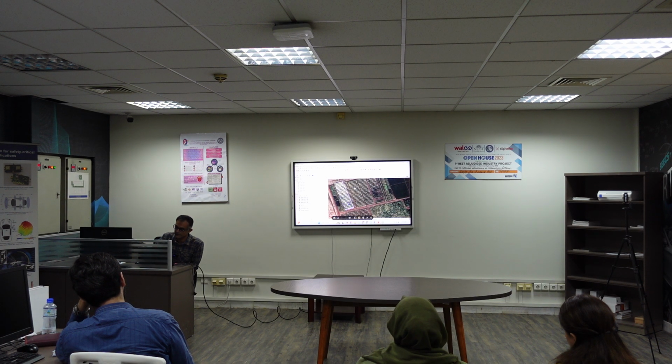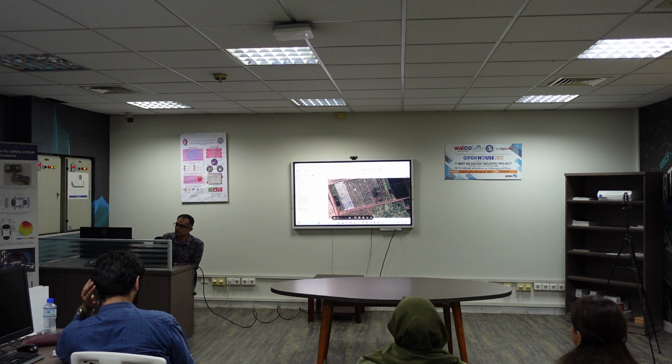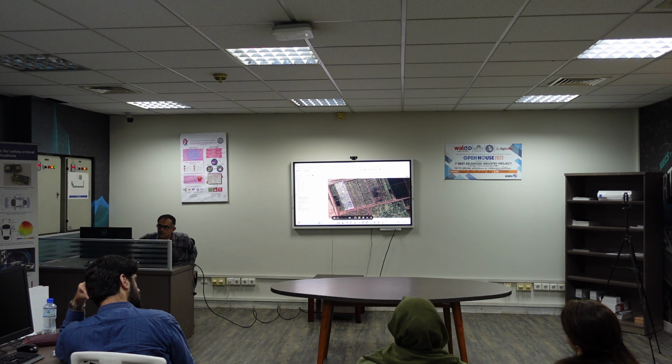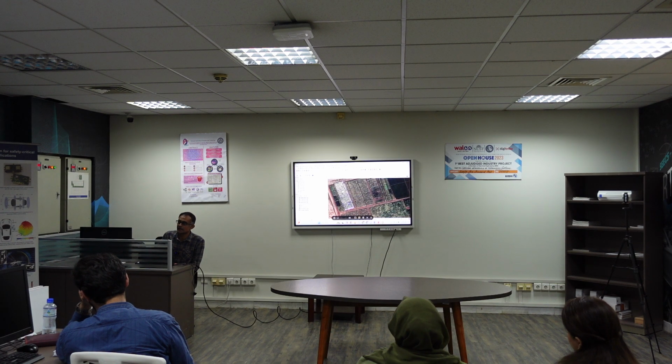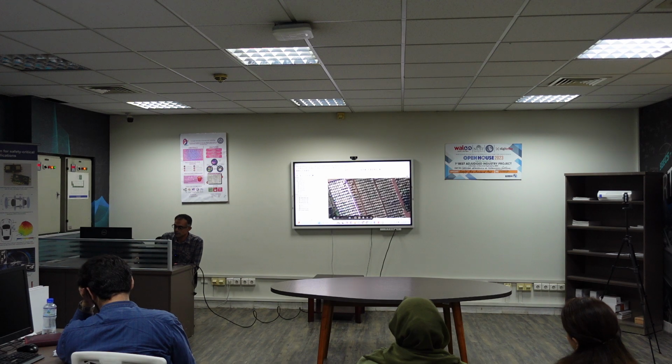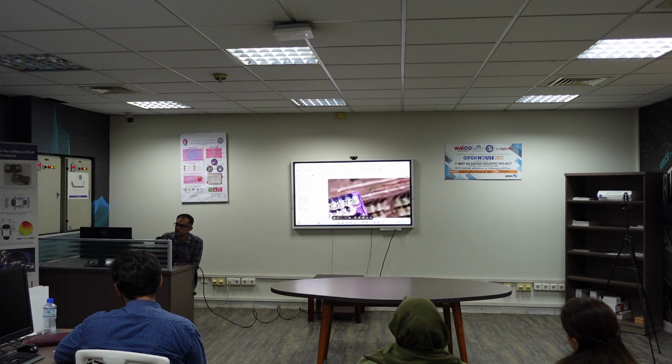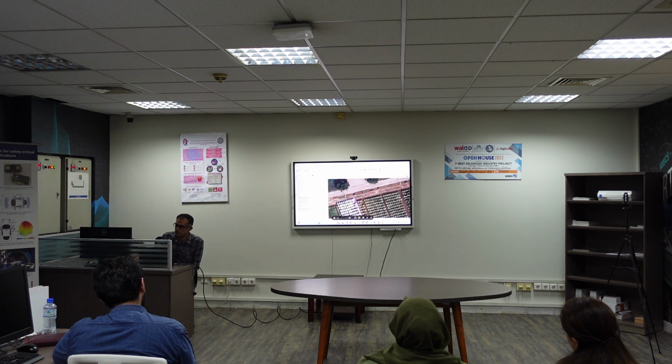I don't know which particular satellite they have used to acquire that, but that is still quite high resolution, and that is not generally available to the public. It is only updated after maybe 3 to 4 months on Google, and that is just RGB. The freely available satellite imagery that we require for analyzing vegetation is Sentinel and Landsat. Sentinel is 10 meter resolution, and Landsat is 30 meter resolution. For context, this is 1.2 centimeter resolution, so it is about 1,000 times higher resolution than the freely available Sentinel 2.